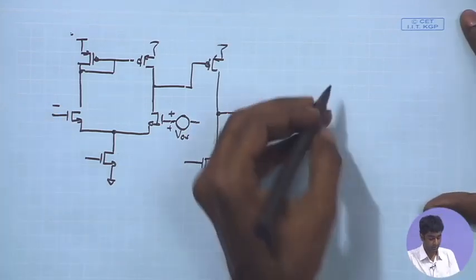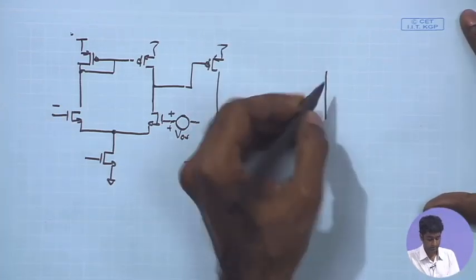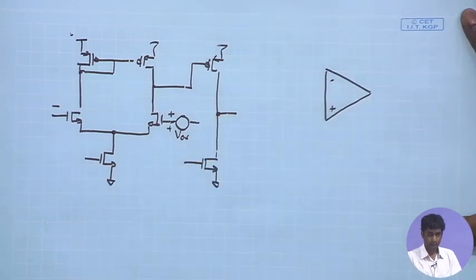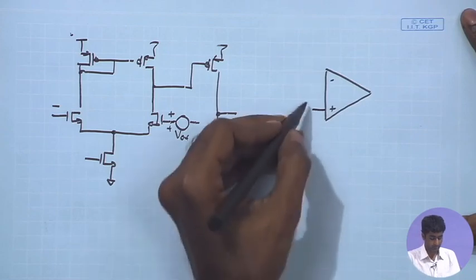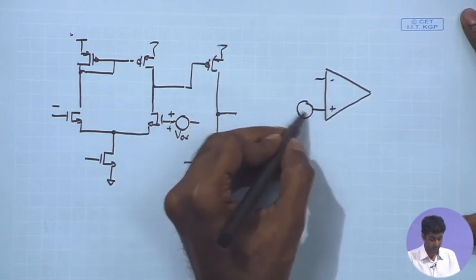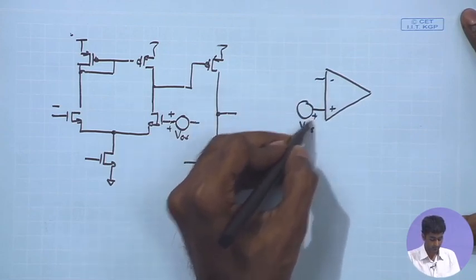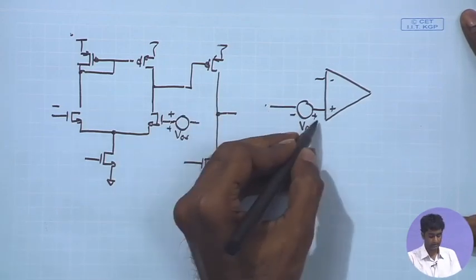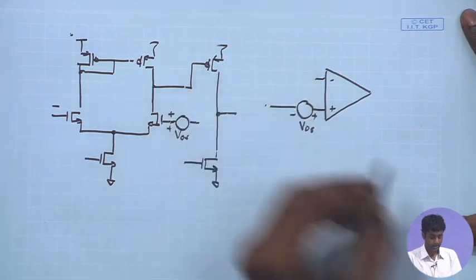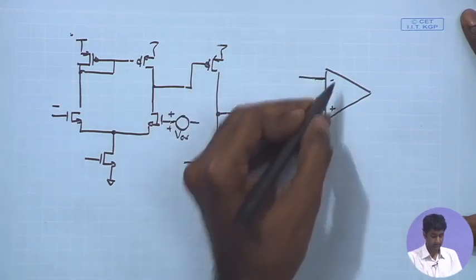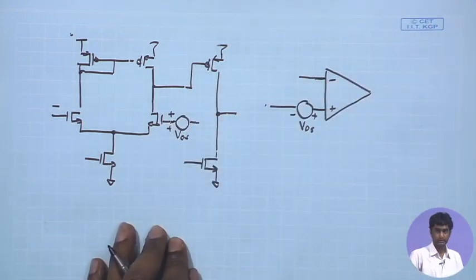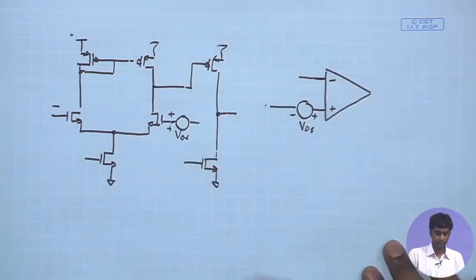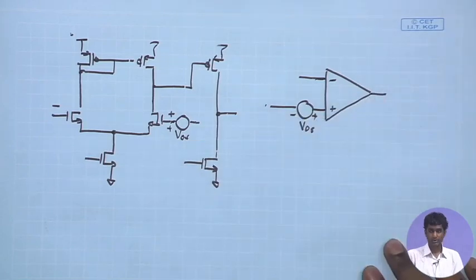And then based on this, we need to look at the overall circuit scheme which can help us mitigate this offset. So, let us now look at the block level implementation of the offset cancellation scheme, where I have the non-inverting terminal. I have applied an offset voltage V offset, keeping the polarity as such. The definition of V offset is the direction I have taken, plus minus in this direction, and I have the other terminal, the negative terminal, as it is. So, this is the ideal amplifier constituted of the transistors of the diff amp that we have over here. It has a single ended output.